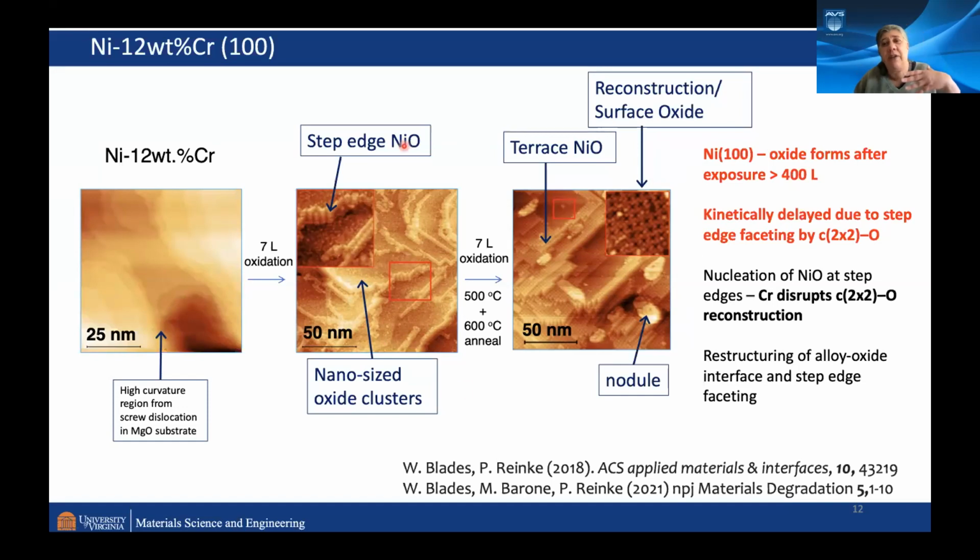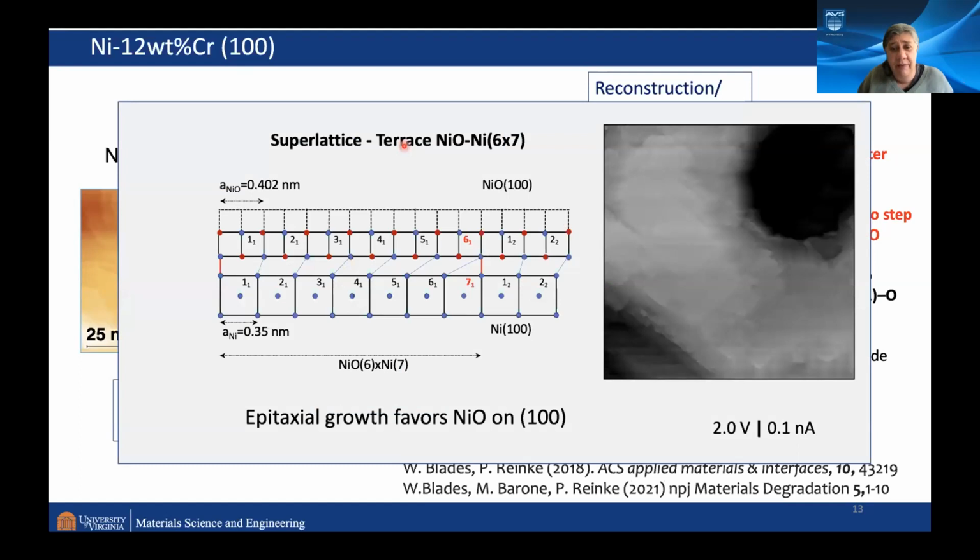So this is the first catalytic or structural effect which you have by doping and going to an alloy from the pure nickel phase. That has consequences because you actually don't want to have the nickel oxide, you just want to have chromia ideally. But you really compete in these very early steps. So why do I know we have nickel oxide?